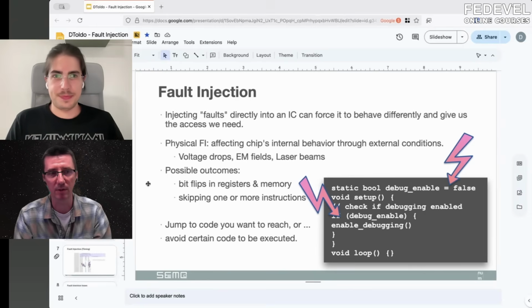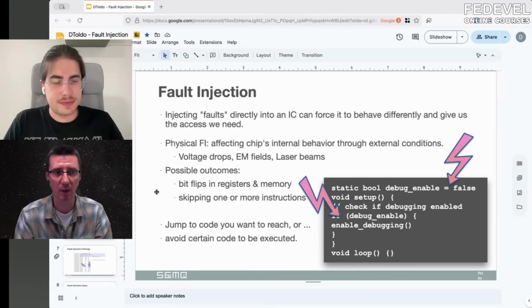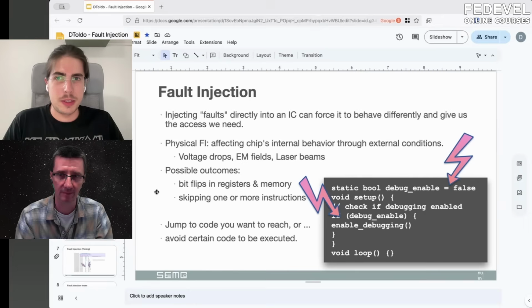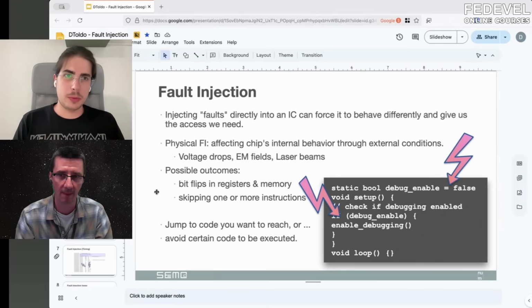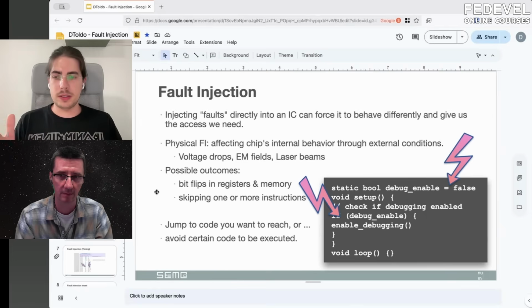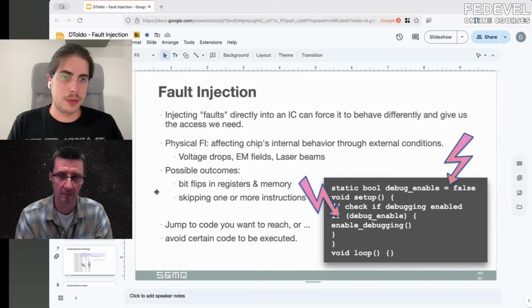But this is interesting because you also need to somehow know the code which is running inside, and how do you get this information? Well, in a real attack, there are some ways where you get the code, like by dumping it. Although dumping flash memory usually requires a debug protocol, and if you need debug access, usually it's also locked.